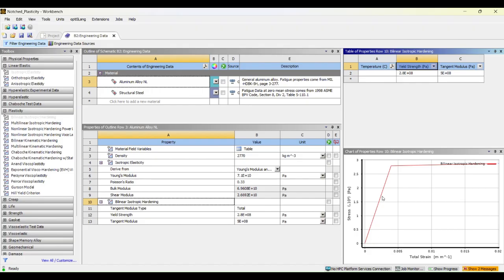There is a linear elastic region, which is represented by this slope here. The slope is the modulus of elasticity. And then there's another curve here that's linear. This is the linear inelastic region. So this is based off of the yield strain and stress and the ultimate strain and stress, and that's the true strain and stress.